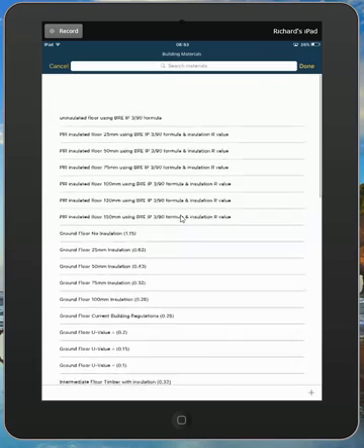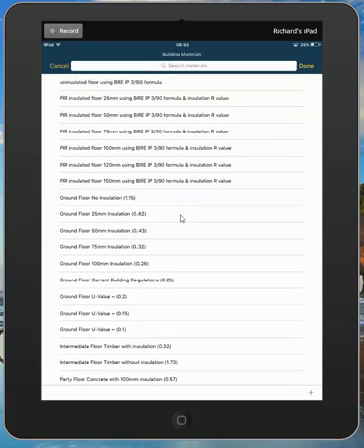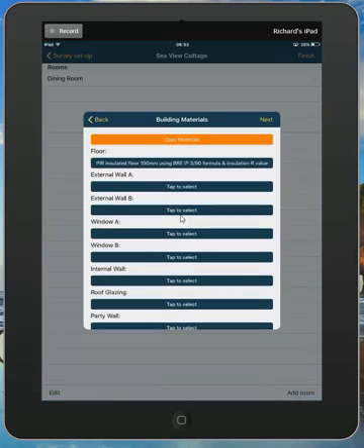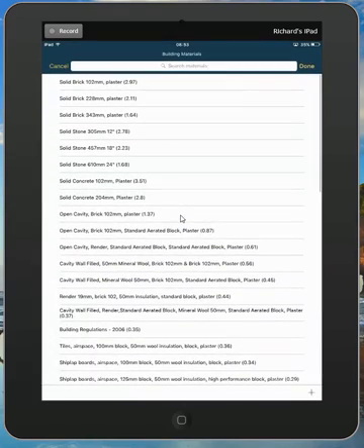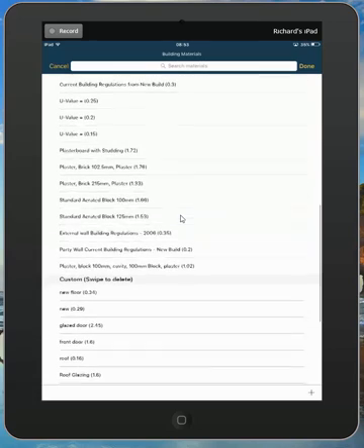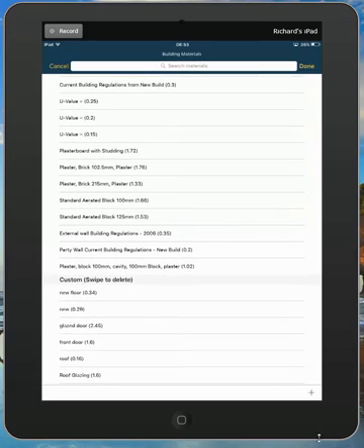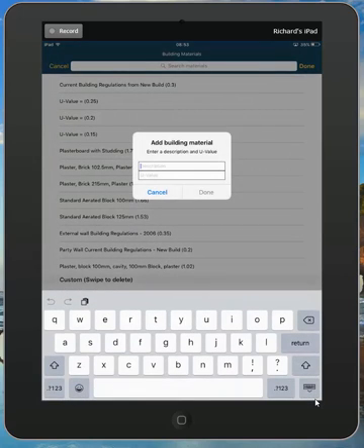in the floor area, so we're looking at the building materials here, so we could say, okay, let's say it's 100 mil of insulation and external wall length. And again, at any building materials you can click the plus at the bottom right hand corner to add a custom building material. Type in the description there, the thickness of each element, so the brick, the insulation, the block, any kind of cladding,